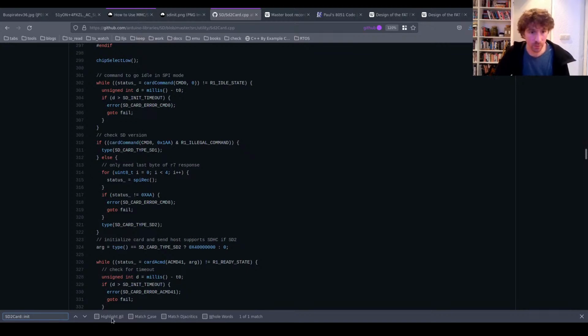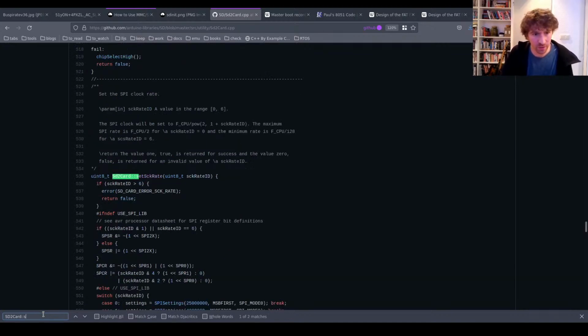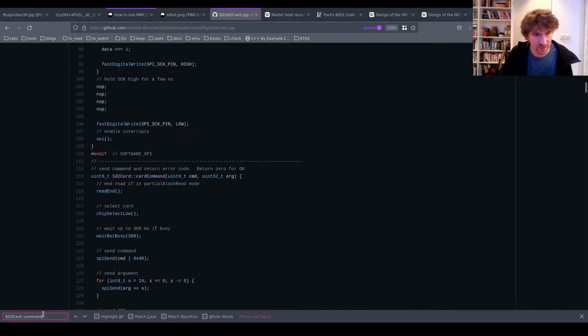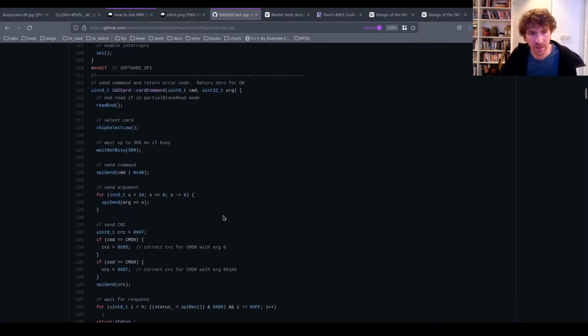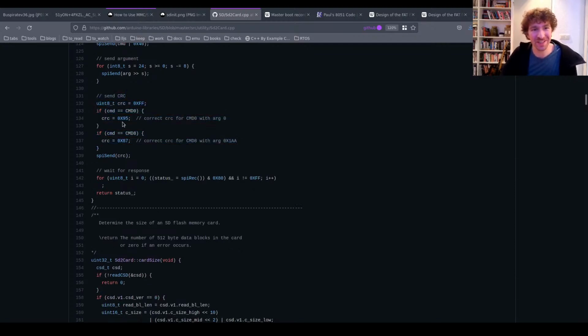Wait, no, I'll tell you where it is. It's in the method that's like send command. Is it send? Is it just command? What's the name of this thing? Card command. That's what it is. Yeah, there is this piece of code, send CRC. If the command is command 0, then we're going to send the CRC 87.